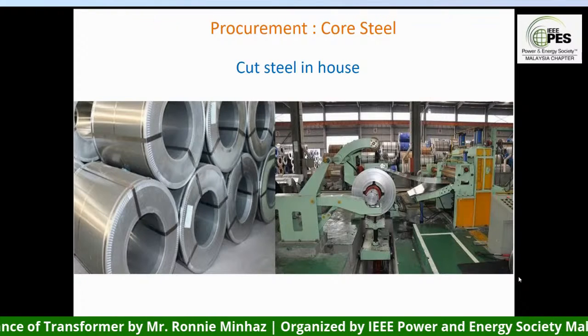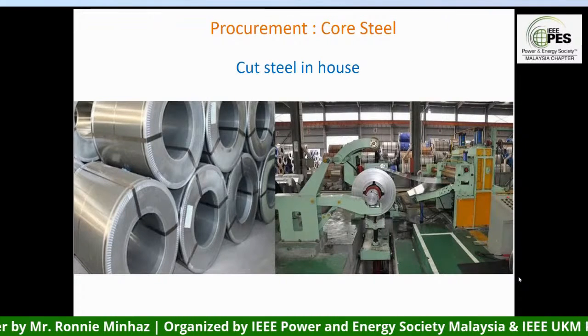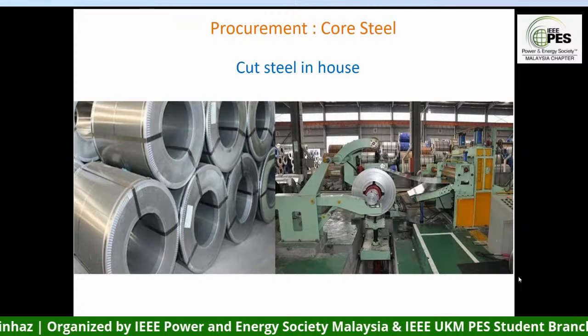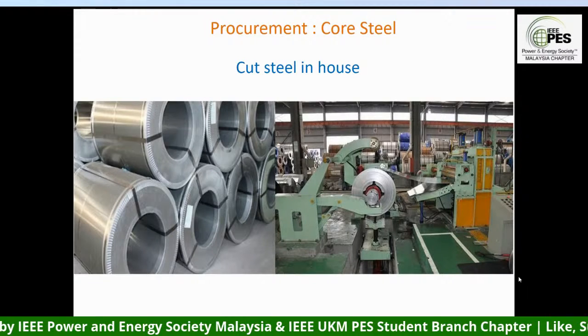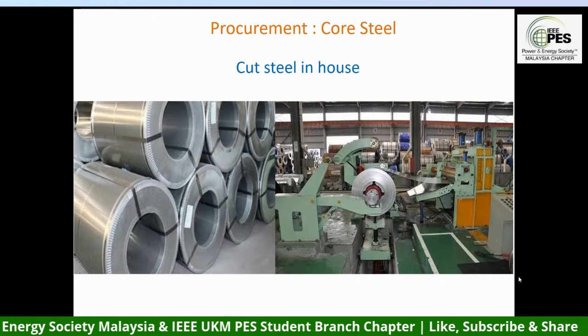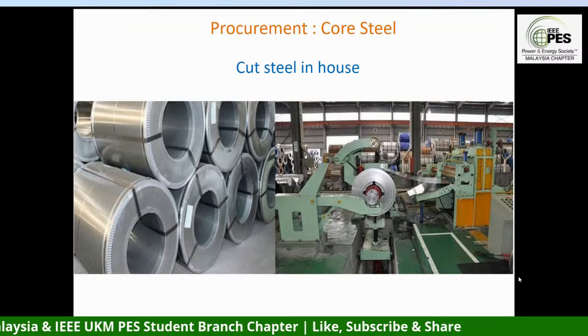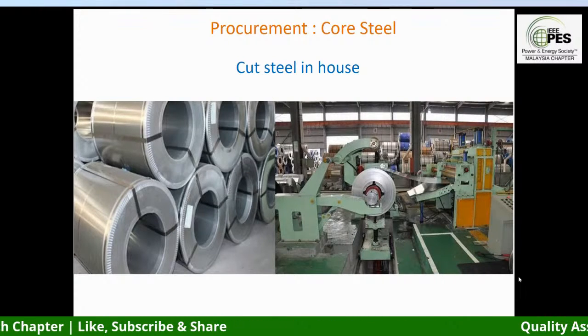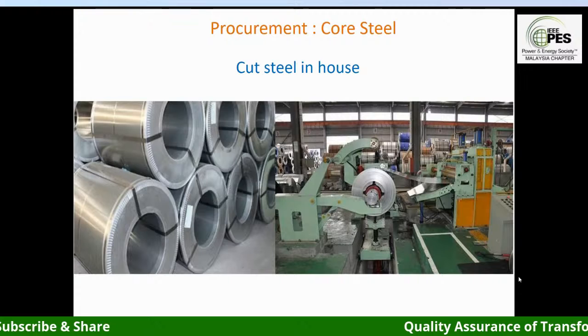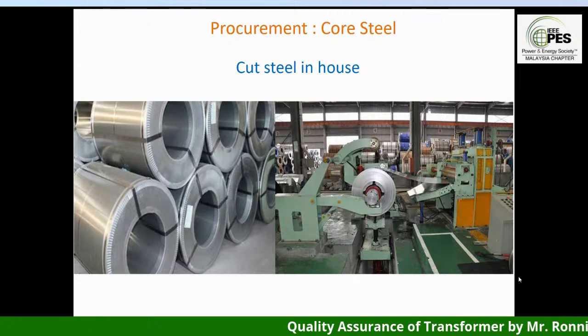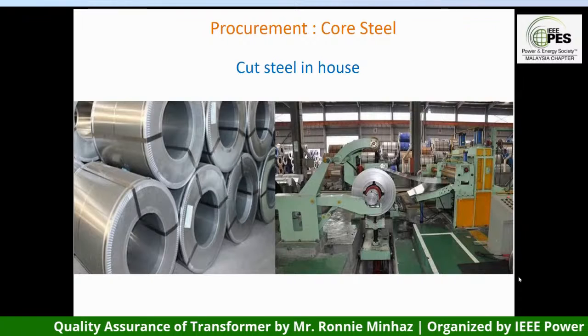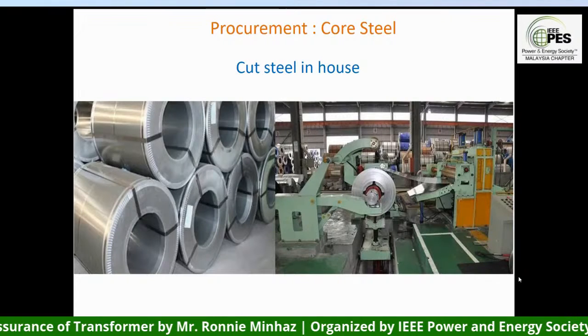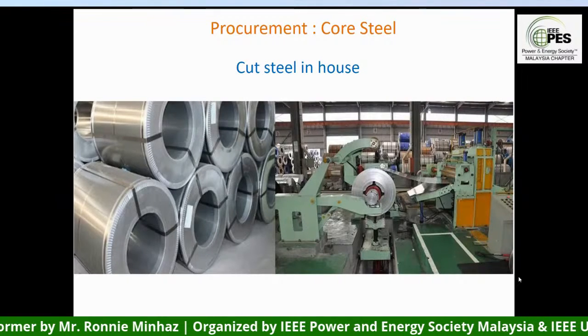The thing is that there is no test. In the factory acceptance test, you cannot pick it up. Not only that, usually when you procure the transformer, those compromises of quality will not show up in the first 5 to 10 years. Usually it shows up after 10 years. So you basically see those disruptions to reliability or the reduction of life, especially after 5 to 10 years of the transformer in service.